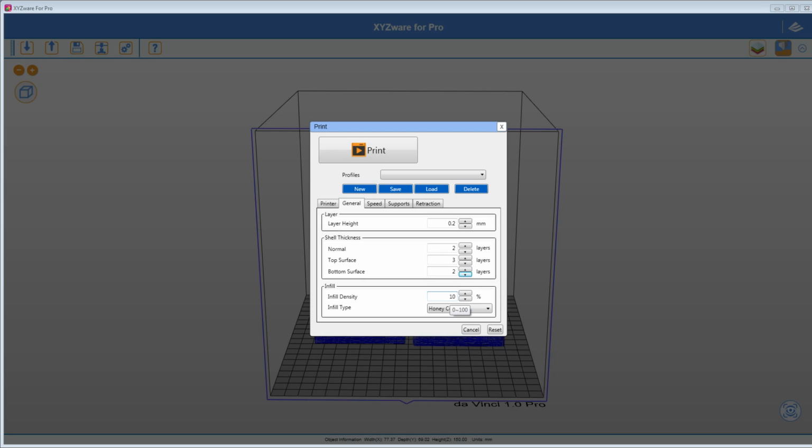And here you can adjust the infill density. Now, depending on what kind of part you guys are printing, adjusting your infill density can speed up the print or make the part a lot stronger, depending on what you're looking for. Typically, for a more artistic piece like this, I'll set it at 10% infill. But if you want to have a very mechanical part, 75 to 95% infill will give you an extremely strong part. Now, for small details, the infill density is good, but don't forget, when you're designing a part, always try to design it with strength in mind.